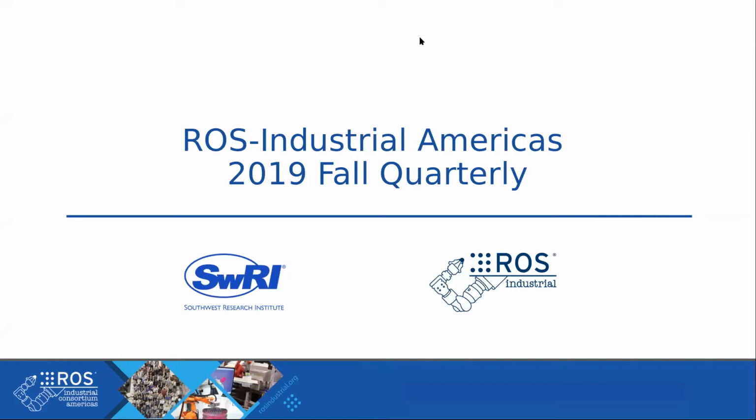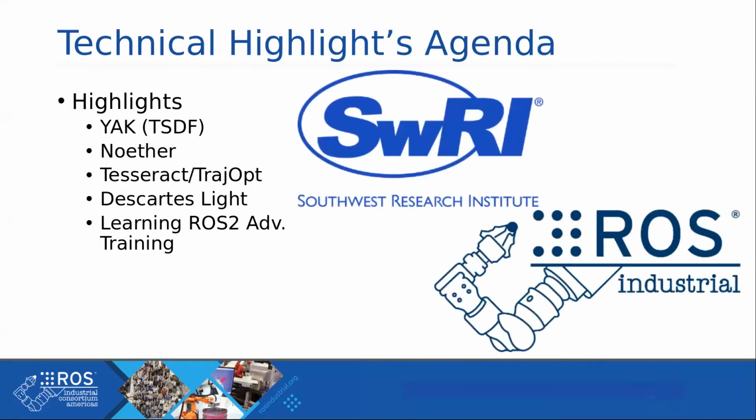Hello, everyone. I'm going to give a brief update on our current technical contributions over the past quarter. Some of the highlights that I'll be discussing are the main packages that we've been focused on related to project work: YAK, which is TSDF for 3D reconstruction. Noether is what we're using for toolpath generation from point clouds. Tesseract and TrajOpt for motion planning, along with Descartes Light and OPW kinematics.